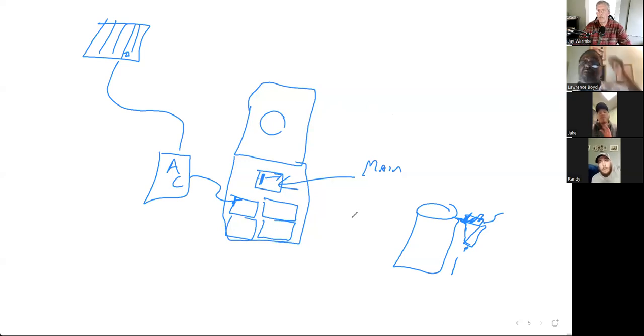Yeah, that's what we were just talking about, and that makes life super, super easy for a solar installation. So then if somebody's got to come work on it, you just come and disconnect that, turn off your AC disconnect, and the whole system's dead.